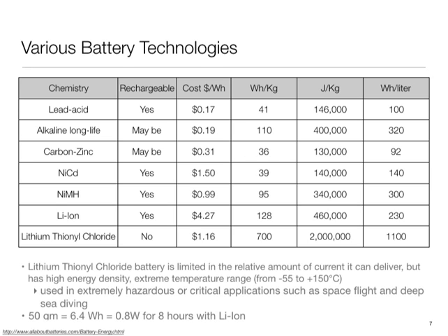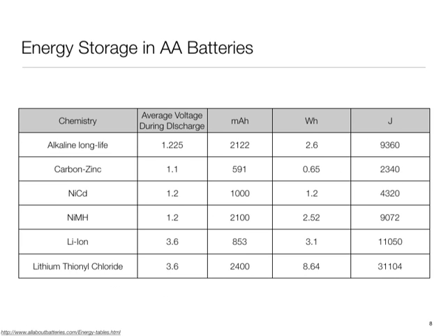Fair bit of variation in how much energy they can store per volume, per unit mass out there, and the cost structures that they lead to. So fair bit of diversity that exists. In some cases, other aspects of the battery besides how much energy they store come into play, like for example what voltage they are able to supply, because your circuit needs certain voltage. So if the battery voltage is too low, you will need two of them in series to supply you the voltage, and that may have implications in size. So all those kind of factors help drive choices of the battery.